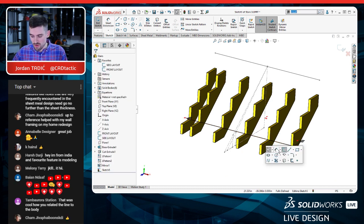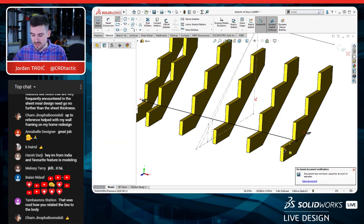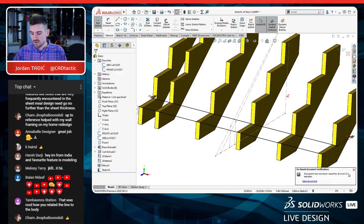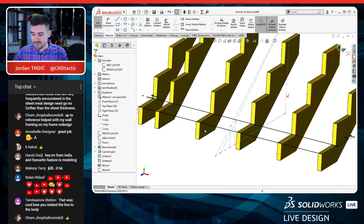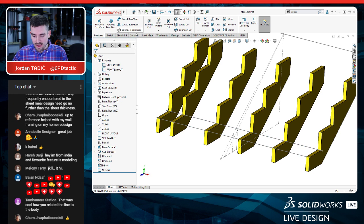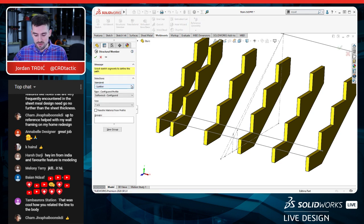I'm going to draw one more line, and this is following up from where Mike Sandy left off with weldments. All you need to do to create a weldment, thanks again for reminding me, SolidWorks, to save, that's a good idea, is a line. So you don't have to create the complicated sketch that I started off with. I could come over to the Weldments tab, and the people that mentioned weldments are their favorite modeling mode already know this. I'm just going to fire up a structural member.